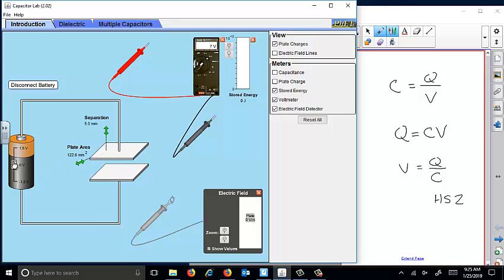But if you apply voltage to this circuit, you create an electric field inside the wire, and so the electric field pushes electrons into this plate and pulls electrons out of this plate. Now, they don't actually go all the way around. It's not like the electrons go up here and over there, through the battery, down there. What happens is the movable electrons that are on this plate just get pulled into the wire here, and then everything gets shifted around a little bit, and then the excess electrons that are here get pushed into the plate. So they don't go all the way around.